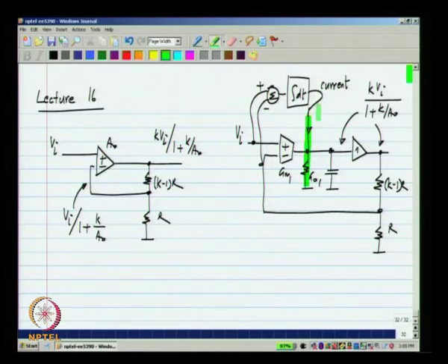So what happens is that after a while, for it to reach steady state, for this current to be steady, the input to the integrator has to be 0, which means that this and that will have to be the same as each other. In this condition, the current that has to go through Go1 will be provided by this path, and nothing will be provided by Gm1. So its input difference can be 0. That is the basic principle.